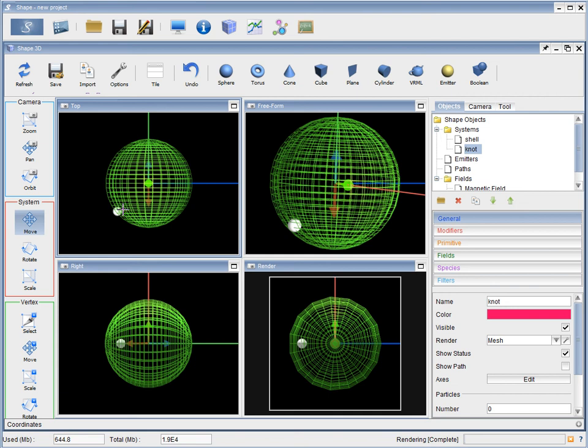Our system transform actually takes along the local coordinate system. The local coordinate system goes with the object whatever you do with the system transforms. You can rotate or scale it, and the coordinate system does the same thing. So whatever modifier you add to it will refer to that local coordinate system. So we have to find a way to move the vertices, the object basically, without moving its transform, its local coordinate system. So we have to undo our system transforms.